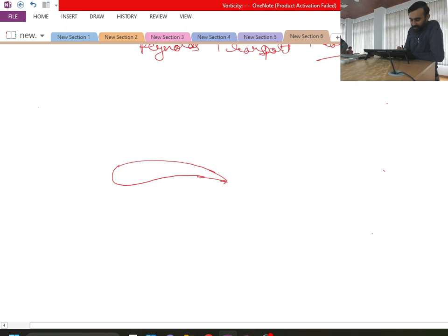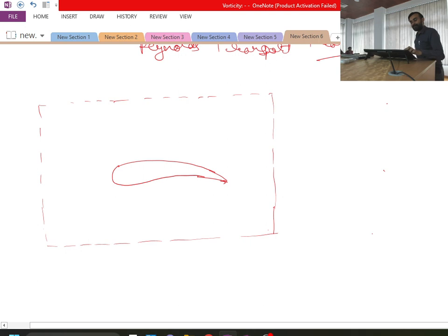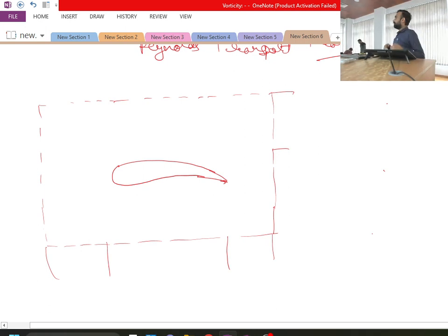So what I can do is consider a region of arbitrary shape, and I define it over here. Why have I defined the control volume only up to this distance in this direction? Why not beyond that? You will find that when an aeroplane is moving, a significant portion of the fluid above, below, in front of or behind the aeroplane gets affected.